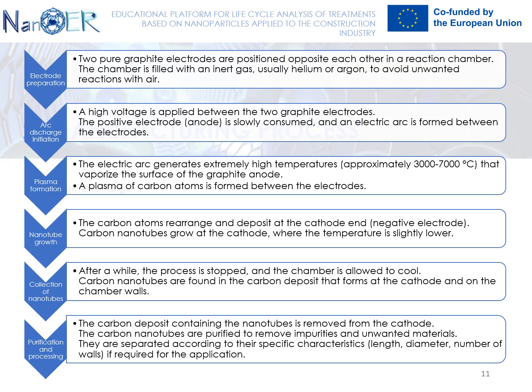The discharge is applied via 2 carbon electrodes which produce an arc by direct current. The electrodes interact with an inert gas which increases carbon deposition. When the pressure of the gas gets stabilized, the power supply is turned on and the positive electrode gets close to the negative electrode to strike the electric arc.